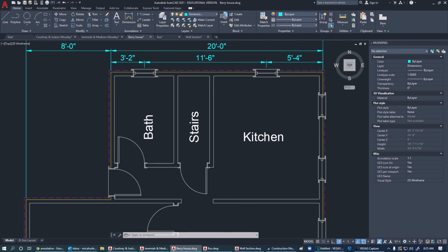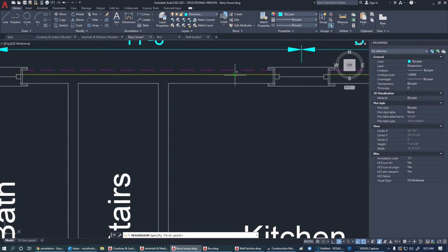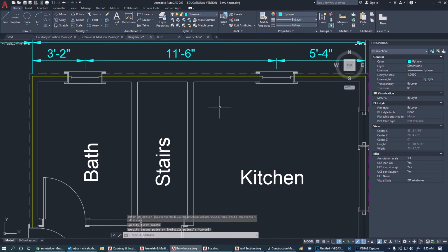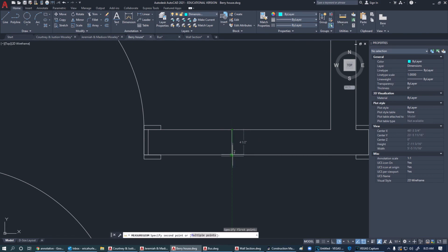Now I have my walls in here, and I want to make sure that I didn't do something wrong here, because all these walls are 4 1/2 inches. It's been a while since I've done this other video, and I drew this. So this wall here has, well, I guess I'm counting the 1/2 inch drywall on the inside, which you really don't want to do. So all of these technically are wrong, because these are 4 1/2 inches. They should be 3 1/2 inches. My bad. Shoot.